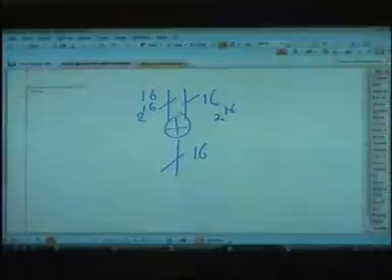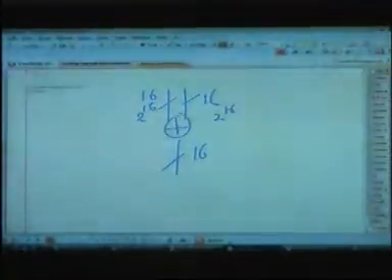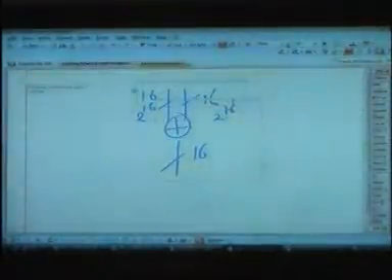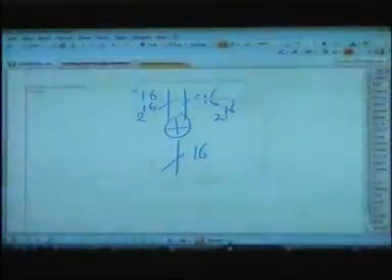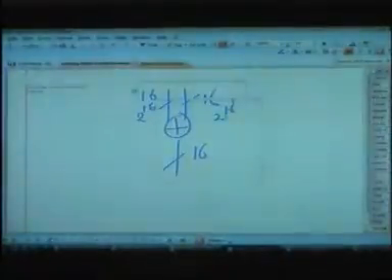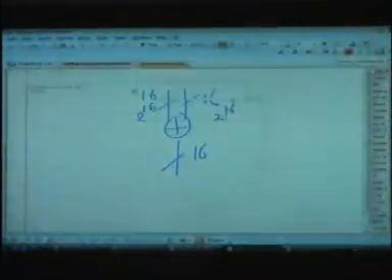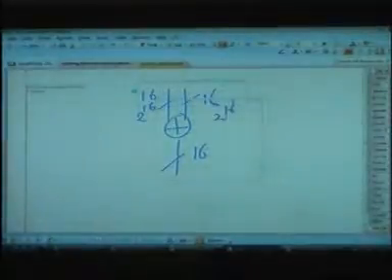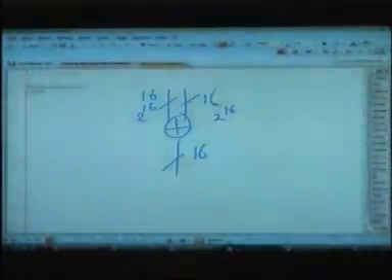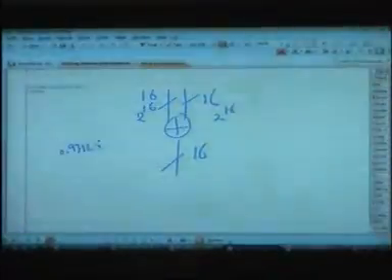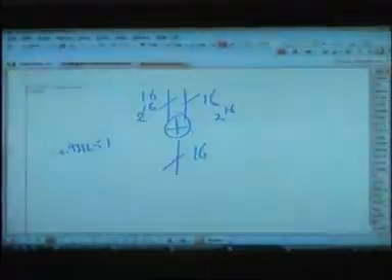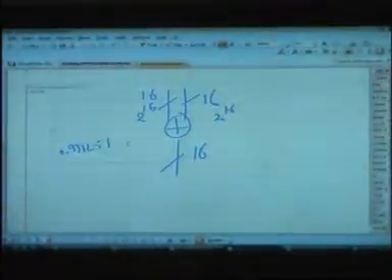That's what people usually don't do. They do it for 1000 values, 5000 values, 10,000 values, and honestly, they'll always find there is a value for which it is not working. For example, we designed a telemetry system, there was a Cordic algorithm in it which computes sine and cosine. I said it's working. Actually, we put everything together and we were testing it on real data, and then we found that for one particular angle, 0.931251 in radian, the design was not working for this value.